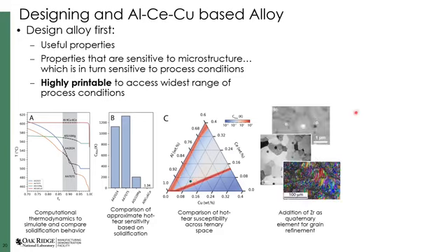We also decided to add some zirconium to this alloy, the reason being that it acts as a grain refiner that gives us some equiax grains that also help us resist hot cracking problems. Also, it means that we'll be able to heat treat this alloy later to form L12 particles, which are good for high temperature strength, although I won't spend very much time here talking about that.